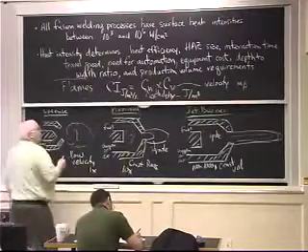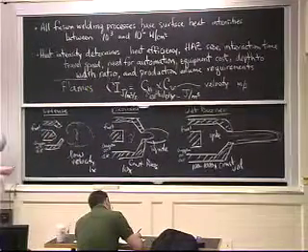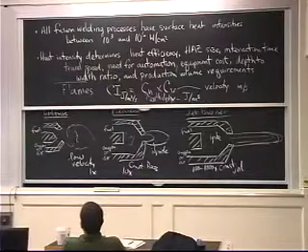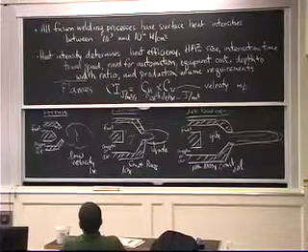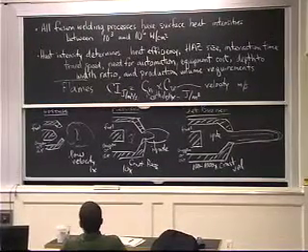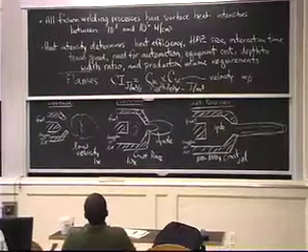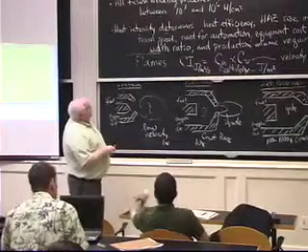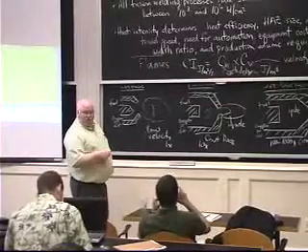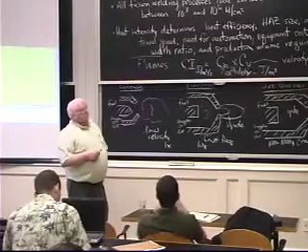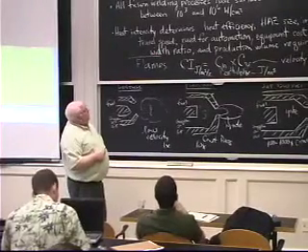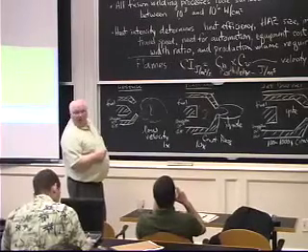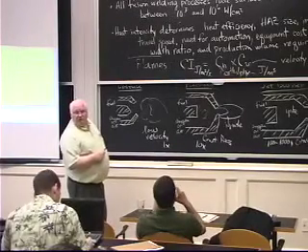But flames go over a tremendous variation in combustion intensity, from something like 1 watt per square centimeter to something on the order of 1,000 or 2,000 watts per square centimeter. Okay? Now, remember up here, I told you that the heat efficiency for flames was about 1%.